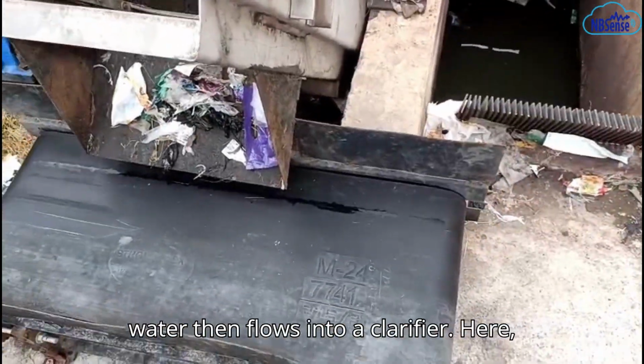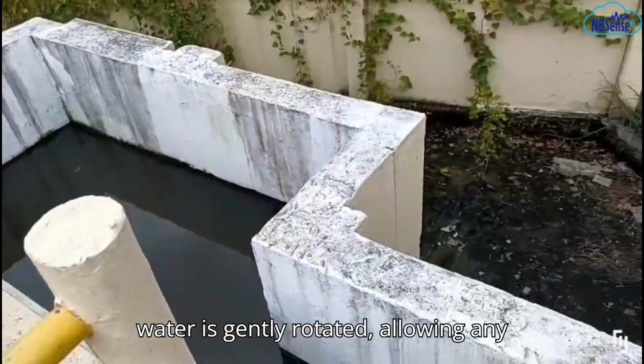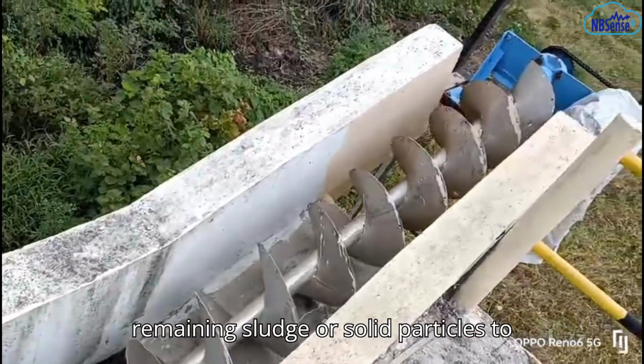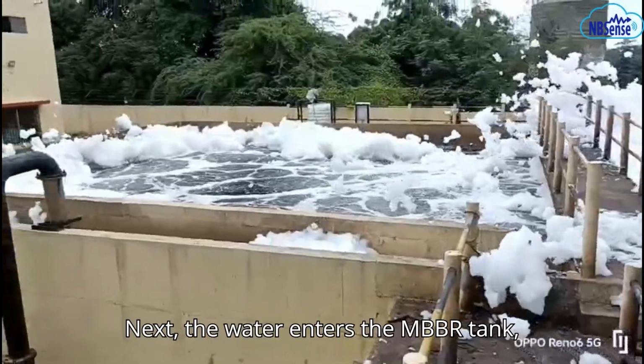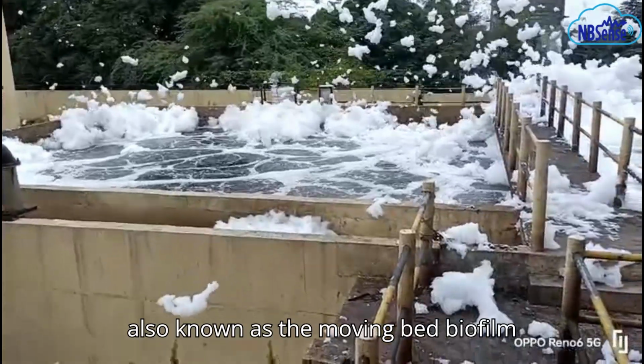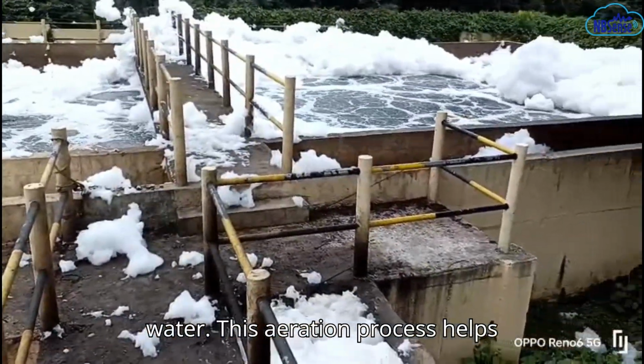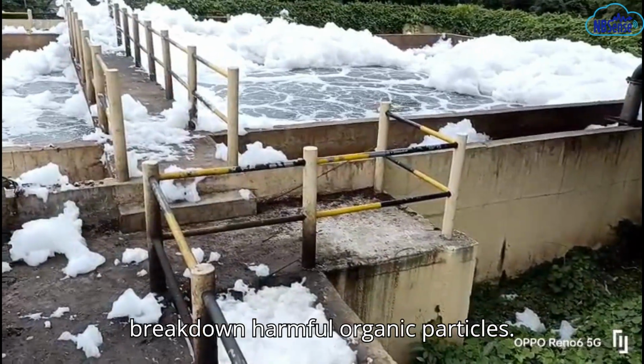The separated water then flows into a clarifier. Here, the water is gently rotated, allowing any remaining sludge or solid particles to settle and be removed. Next, the water enters the MBBR tank, also known as the moving bed biofilm reactor. Here, air is pumped into the water. This aeration process helps break down harmful organic particles.